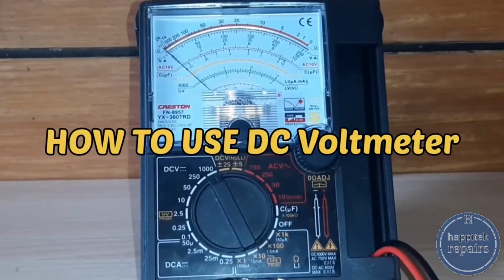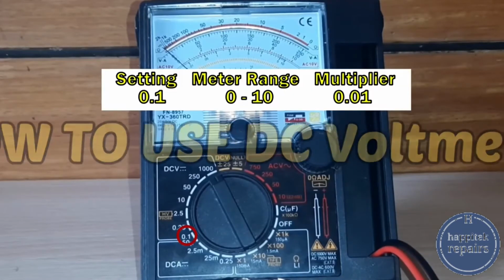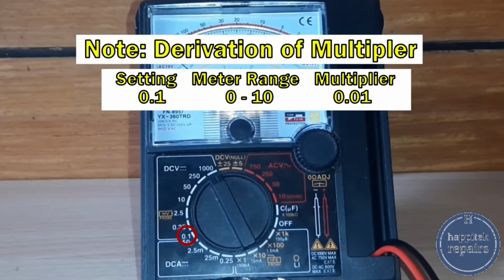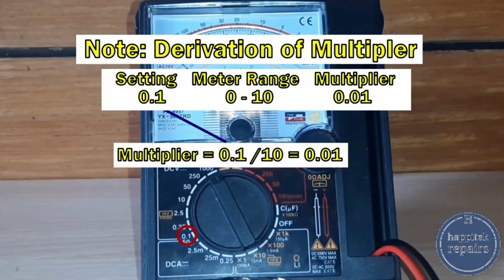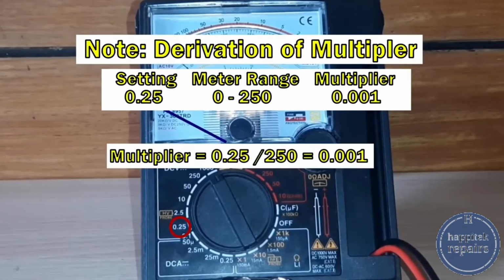For the AC voltmeter, these are the settings that we can use. For the 0.1 setting, the meter range we should look for is 0 to 10, with 0.01 as a multiplier. That is derived by dividing 0.1 by 10. For 0.25, 0 to 250, multiplier 0.001.